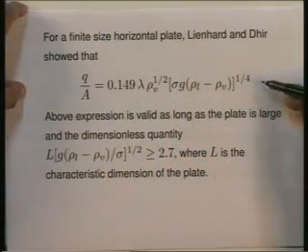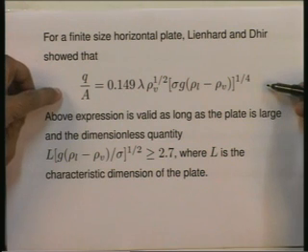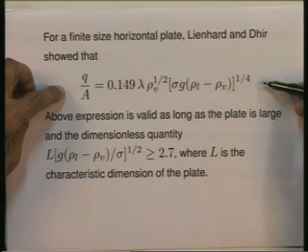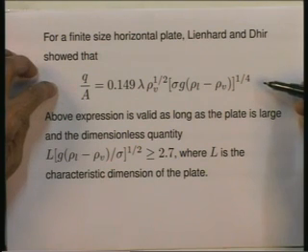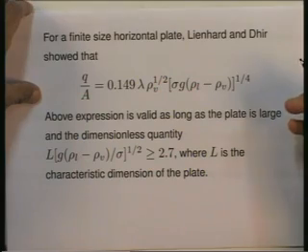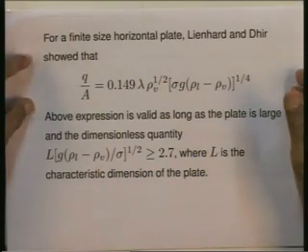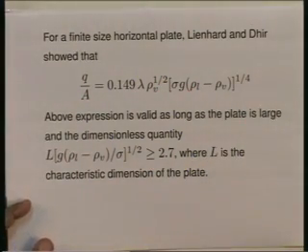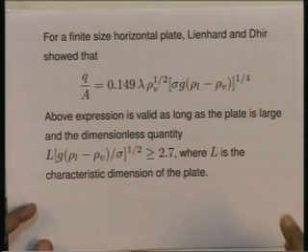So, for calculating peak heat flux, the preferred expression is the one given by Lienhard and Dhir, which is Q by A equal to 0.149 lambda rho_v to the half into bracket sigma g (rho_L minus rho_v), the whole thing to the power of 1/4. This is the expression that is nowadays preferred. There are expressions for other geometries also.